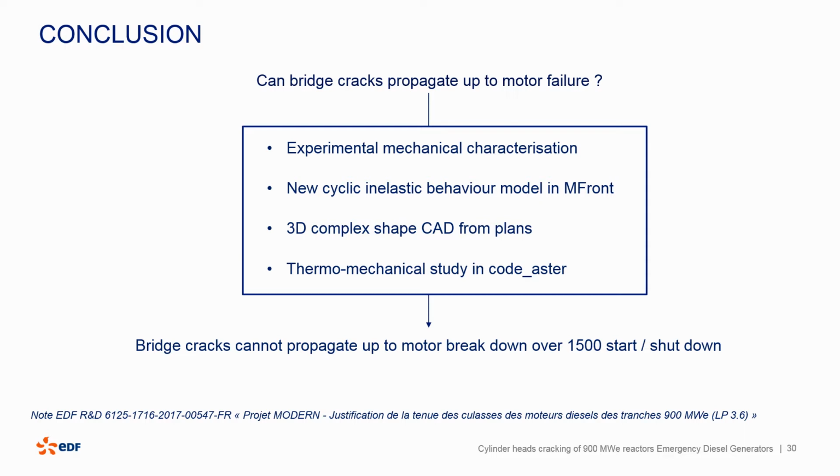Yes? To better understand how you simulated the cracks, did you detach the nodes locally, or did the software that you used make this in a sort of automatic way based on the stress level? Yes, so the crack propagation was performed explicitly, if I dare to say so. The length of the propagation was not computed by software. We could do it, but we didn't see the point in this case because we had to analyze different crack sizes anyway. In the way to produce the mesh, the nodes are doubled and you add the discontinuity.